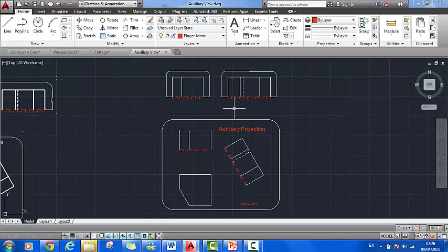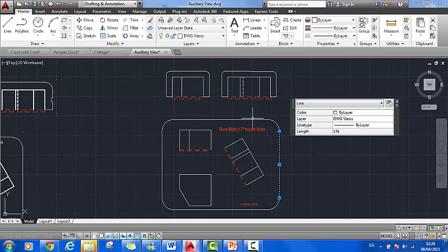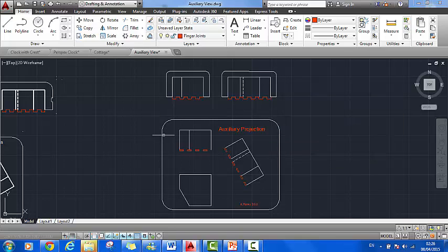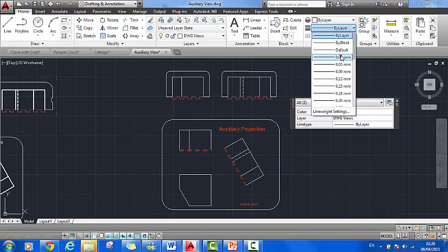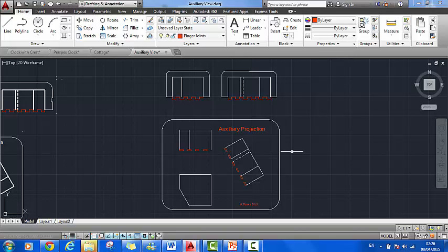The only remaining thing to do here is to actually set all the lines to your zero thickness, or to your etching thickness. This has already been shown to you in previous tutorials, but just to give a very quick overview of it. This base here, all of this base, needs to be cut out, as well as the orange rectangles there that we see. So we need to set those to, if you can remember, a thickness of 0 millimeters. That's a cut, it's a vector cut.